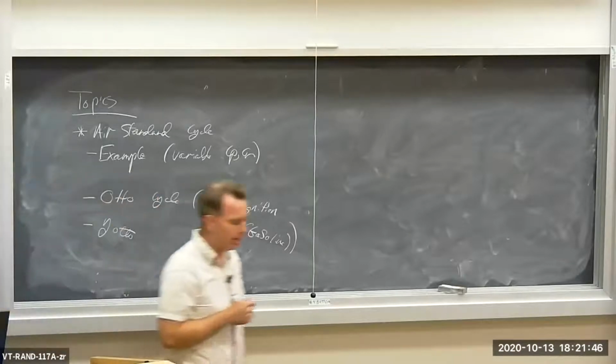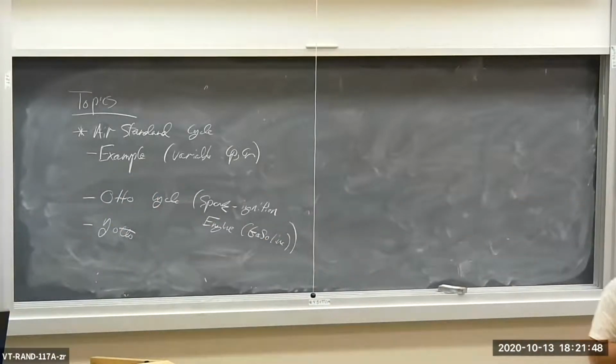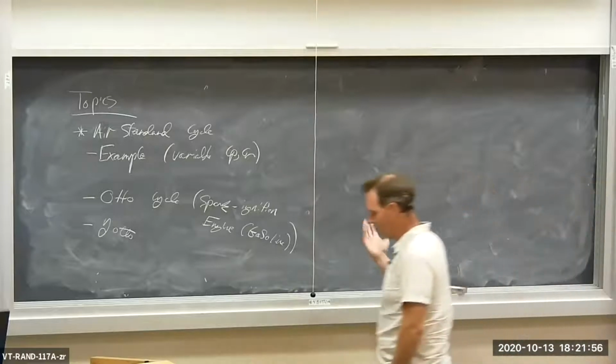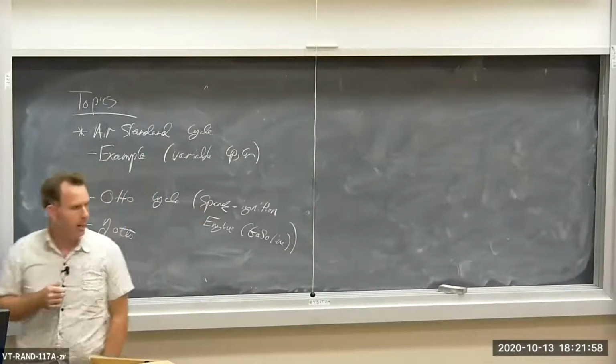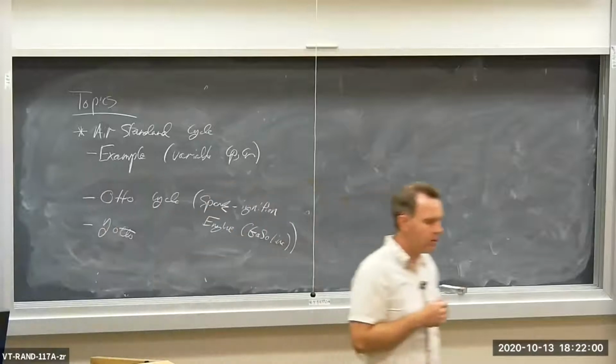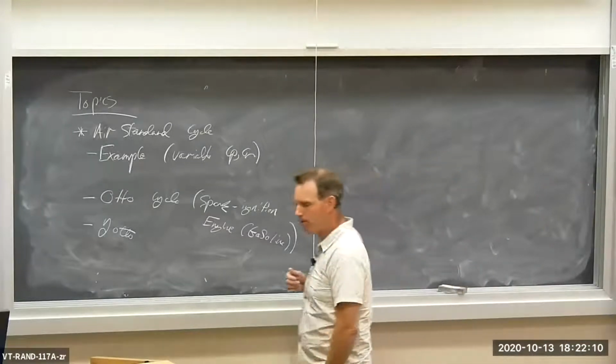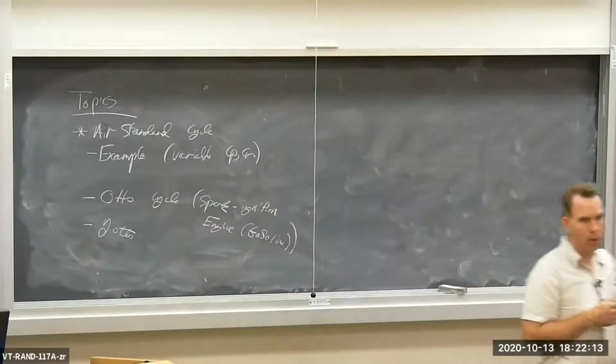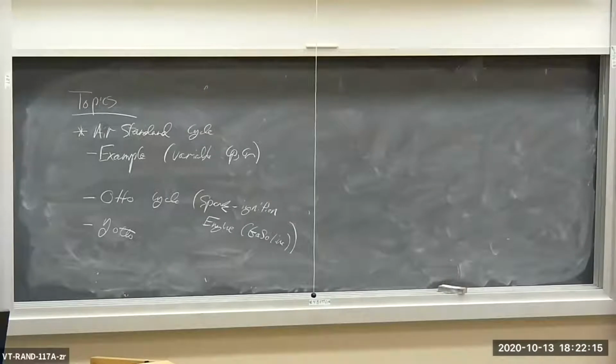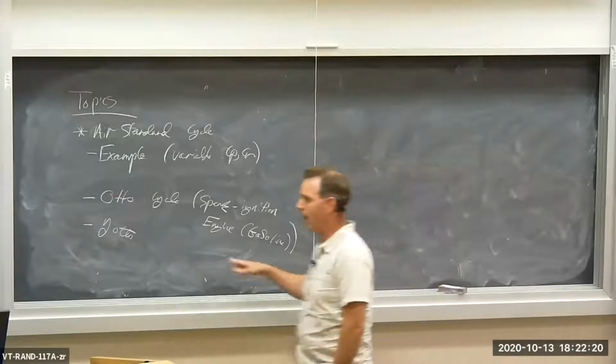Get your feet wet, not your face, your feet wet, applying the principles that we learned last time to calculating efficiency, heat addition, various quantities for an air standard cycle, and then we'll move on to analyzing a very common air standard cycle, which is the Otto cycle. The Otto cycle is the approximation of the internal combustion engine that's probably in your car. So any spark ignition engine, any gasoline engine approximates an Otto cycle.